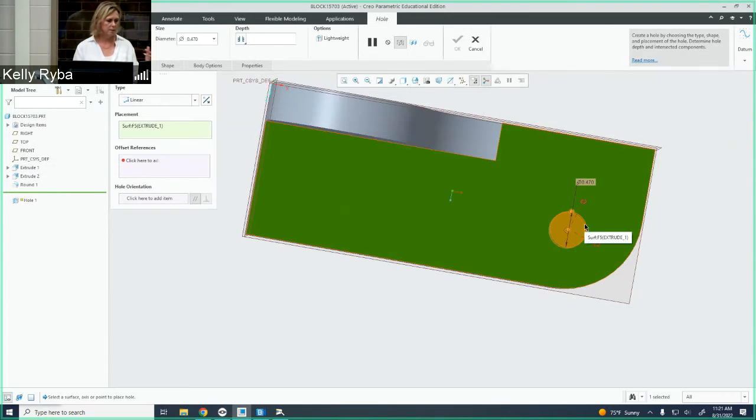Now, there's a diameter that they have in there as a default value. We're going to put in a 1/2 inch, okay? So up here is where the diameter size is, up on the top there, or you can click it directly in the sketch here, which is actually probably more efficient, so I'm going to do it there. Double click on it, 1/2 inch, enter.